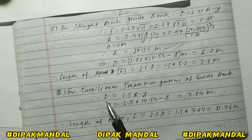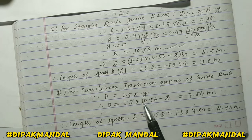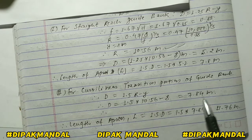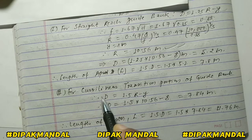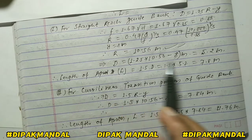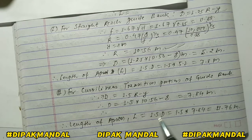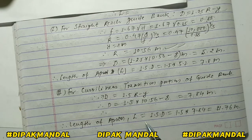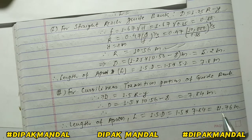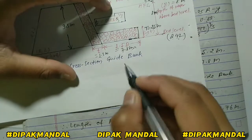And after calculating D equal to 1.5 (R minus y), R is 10.56 minus y is 8, this value becomes 7.864. Okay, only the value of D changes. Okay, in the above this value is 5.2 and in this one the value is 7.86, and we can calculate length of apron L equal to 1.5 D, and we use this value, so the length of apron becomes 11.76.